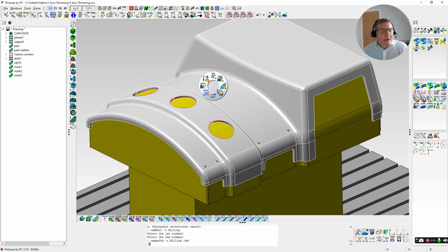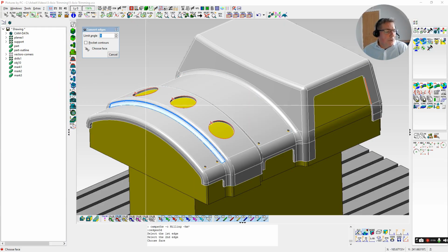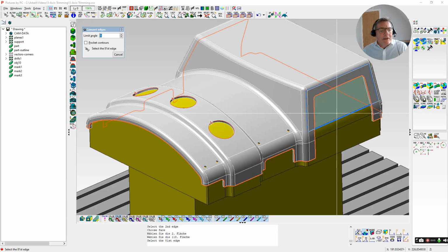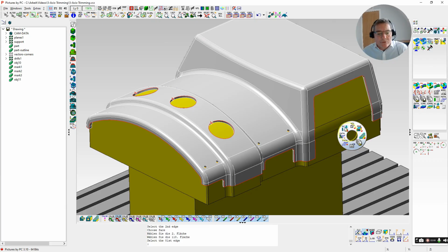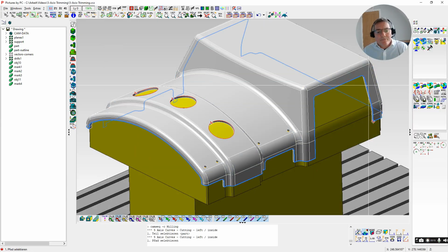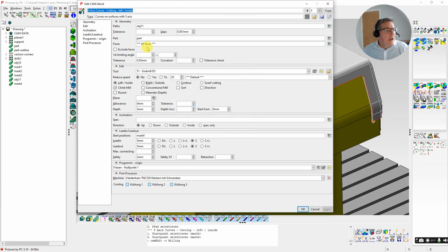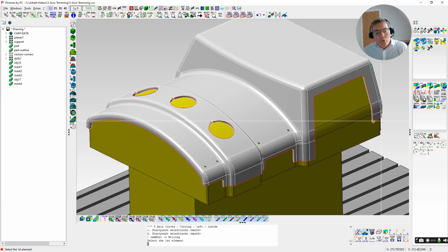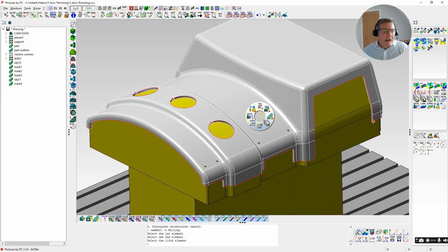We're going to repeat this around the outside, so I'm basically going to create an outside contour here. Use the feature recognition to select the outermost faces and convert their edges into a machining contour. Point marker to lead it onto. Load a 5-axis cutting operation and select the geometry as we did before. Edit the operation. Again, we determine the tool orientation through the surface selection. I've selected all of the outer surfaces, and we'll simulate that.